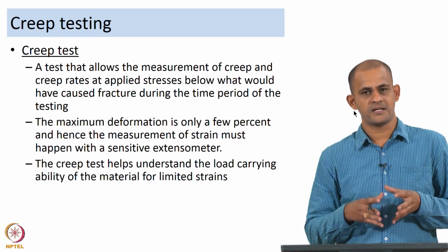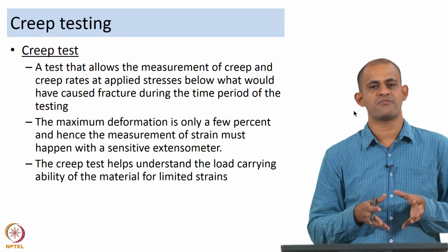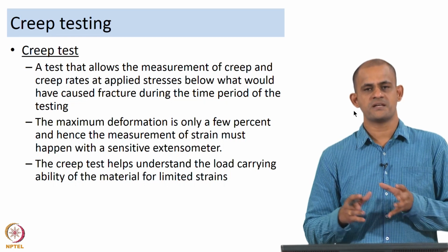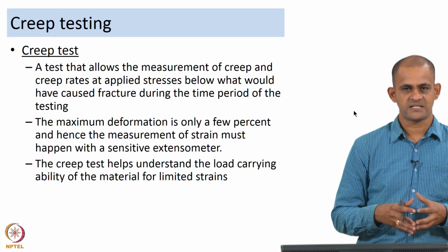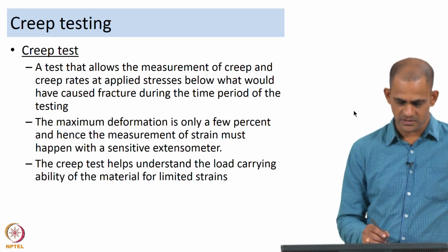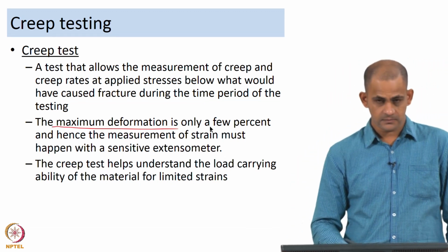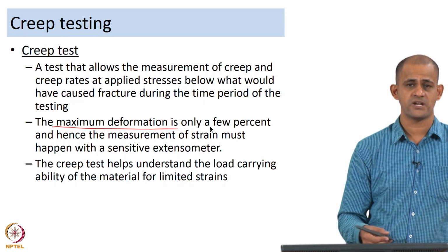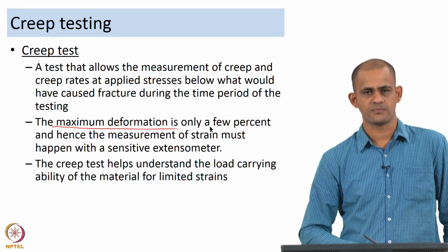In this particular type of test, your focus is only on measuring the amount of deformation that the material undergoes in a certain time period of testing, and typically the test is carried out only to a few percent of plastic deformation. So, the maximum deformation that is allowed in this kind of test is only a few percent, and hence the measurement of the plastic strain requires the use of a sensitive extensometer.